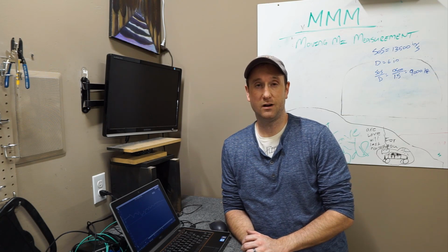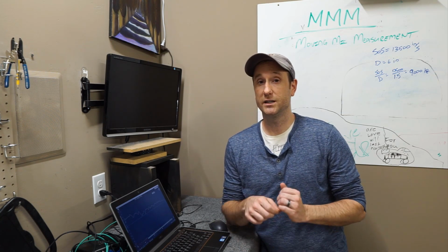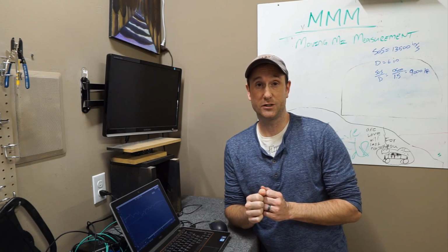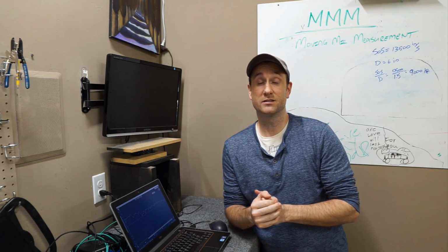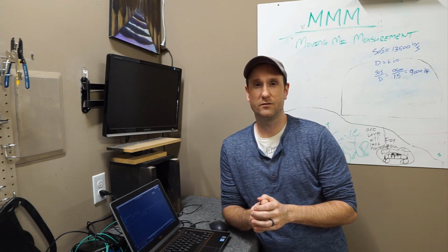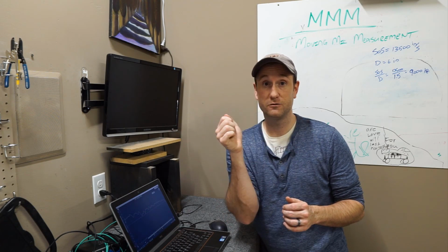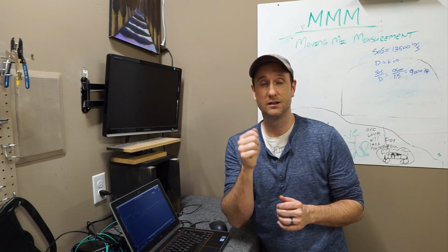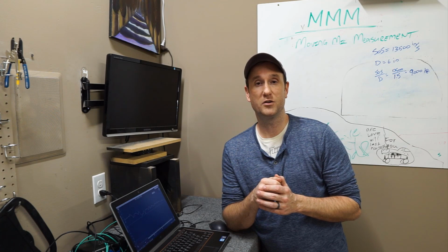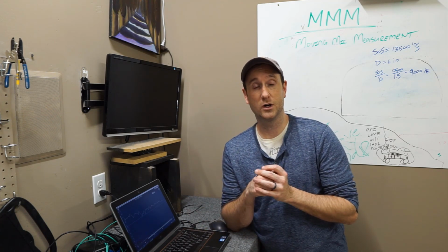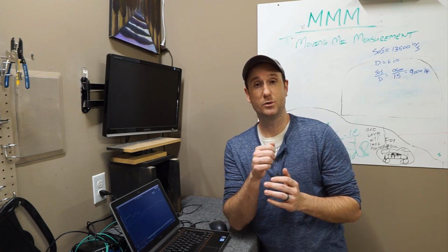This benefits you because you are no longer taking just a single point measurement, nor are you taking multiple measurements and averaging them. And I'll tell you one thing that beats is if you were to do any of these kind of methods that we discussed before, such as single microphone, multi-microphone and average, or the sweep across your face while you're sitting in the seated position, every time that you do that, you have to pause the measurement and make adjustments on your laptop or your DSP software, and then go back to that measurement process again.